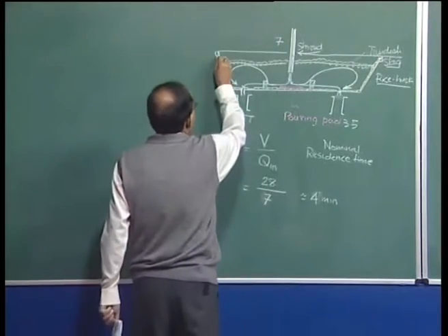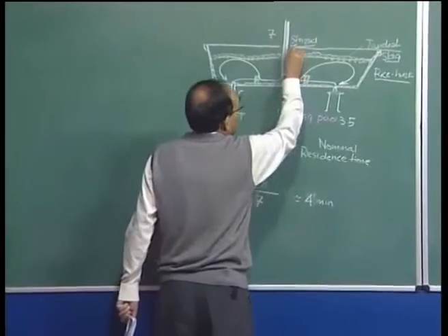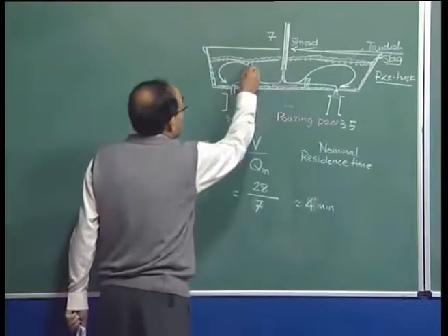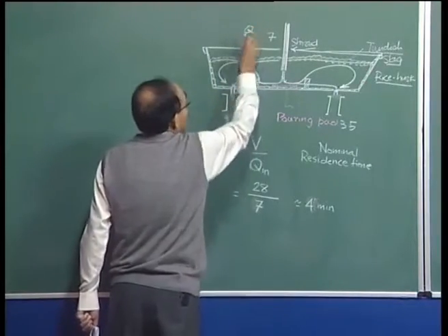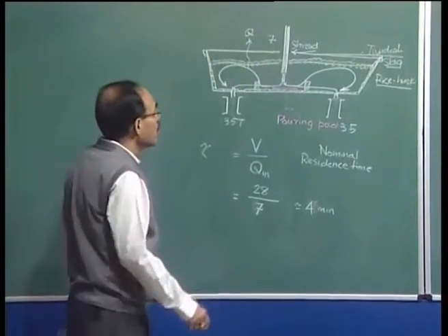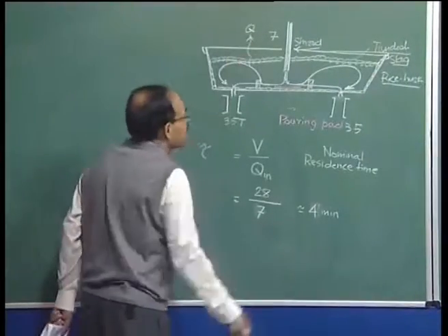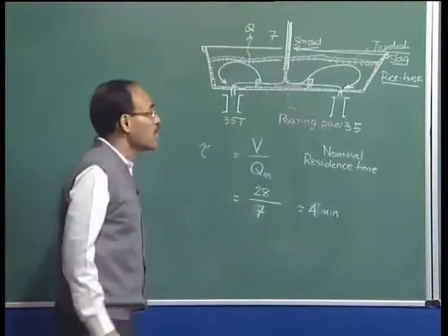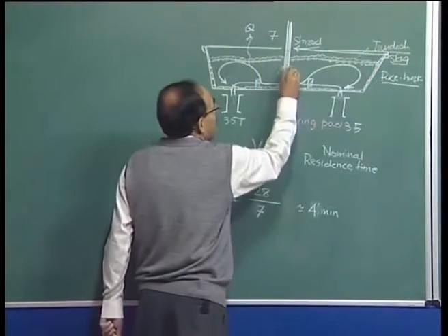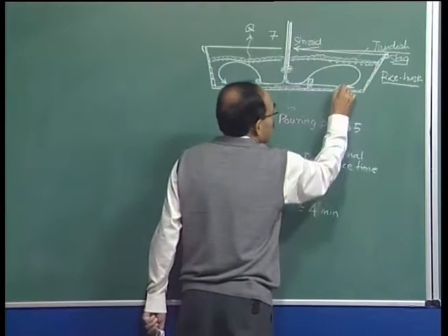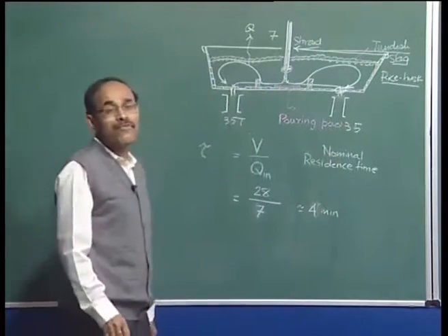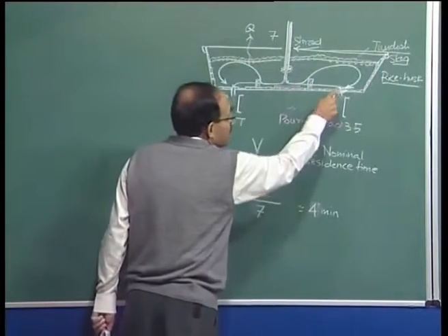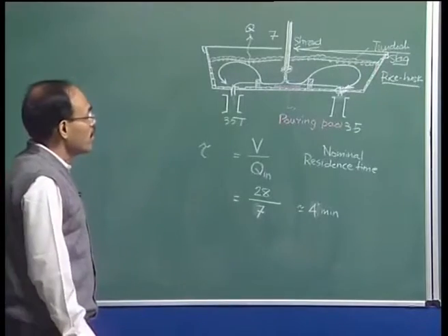So, because of this large surface area, we have to have tundish covers also, and these tundish covers really prevent a lot of heat loss. Not much heat can go out of the tundish, as the wall reflects the heat back. As a result, even though the surface area may be very, very large, the drop in temperature of molten metal at this location and at this location is barely 5 to 7 degrees centigrade. So, if it is 1660 here, it could be 1653 here, 1654 here,